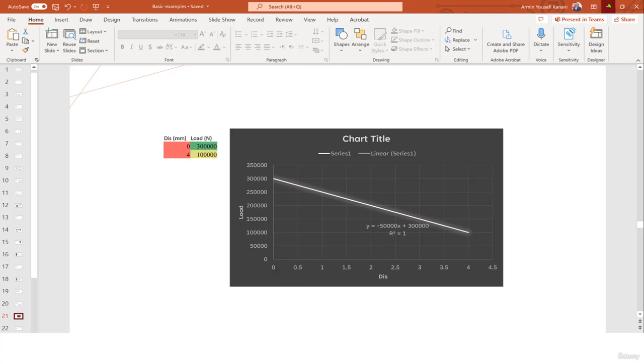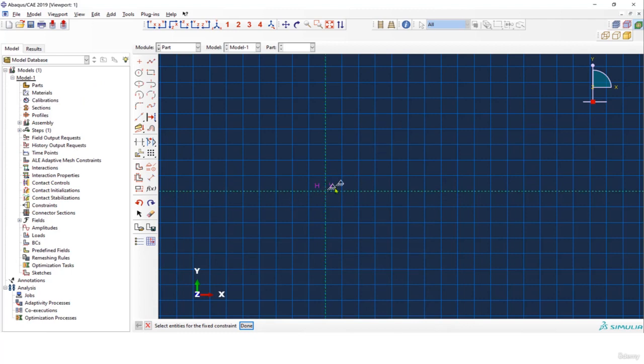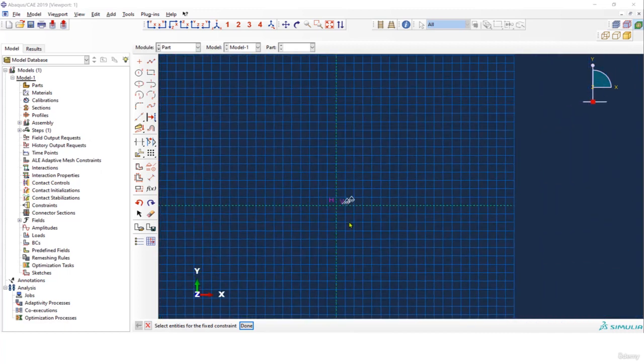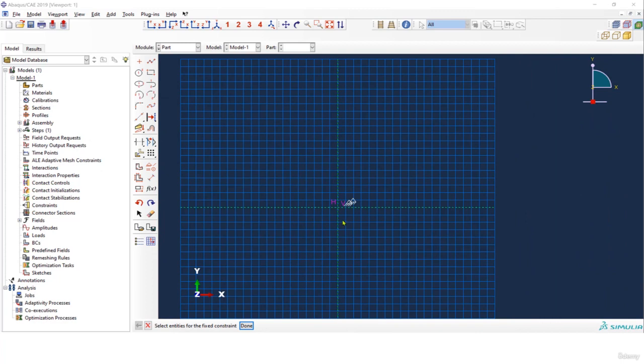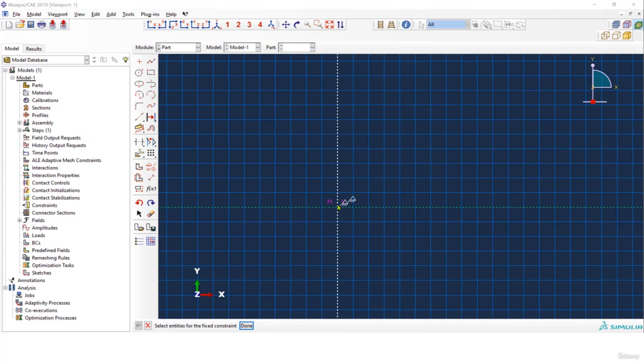So if you don't actually know where the 0, 0 point is in comparison to your model, you're going to be in trouble. To make this clear, I will first generate this one, and then I will show you another example where the start of my sketch does not start at the 0, 0 point, to make this more clear for you and why it is important you know the location of the 0, 0 point in comparison to your model. Okay, so now let's start by drawing a line.